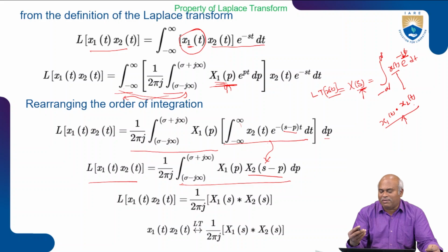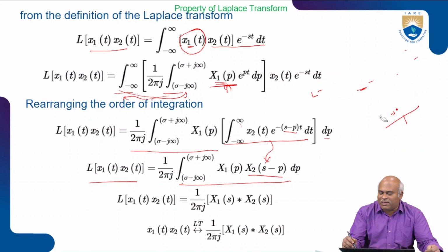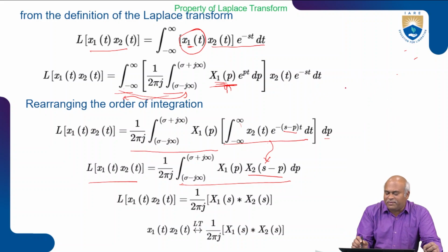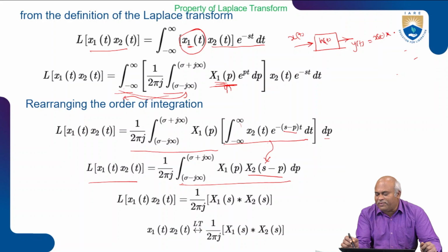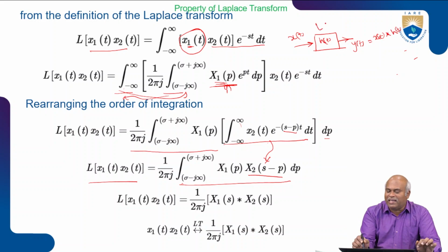We know the time convolution, what the formula represents. The time convolution of the signal: for a system, we pass x of t. The system response is represented as h of t. This is equal to y of t. The y of t is equal to x of t convolution h of t. We wrote this as the case of an LTI system.